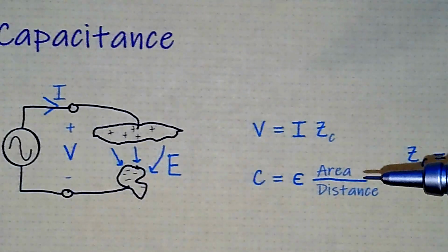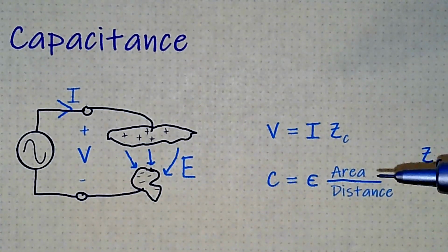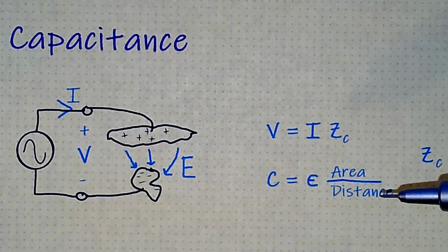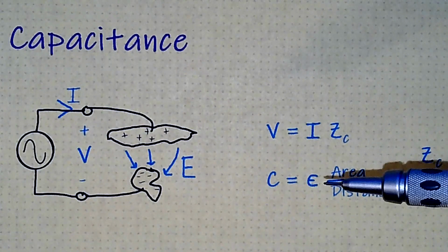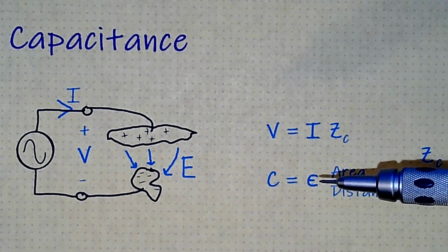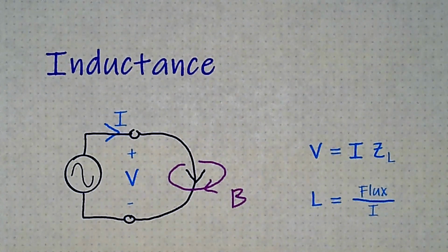The capacitance itself is a function of how big the stuff is, what the separation distance between it is, and what the permittivity of the material that separates them is. Lastly, before we go back to the resistor, and the real issue today of parasitics and radio design, because you have to know how parasitics exist in order to design a successful product, let's look at inductance.